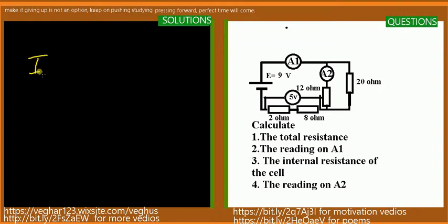So let's try this current divider rule to see if it is true, because Ohm's law says the current in parallel divides itself. If the total here is 0.5, it divides according to the ratios. The ratio means that if the resistor here is lower than the other one, this side will have higher current because the resistance is low, and this side will have lower current because the resistor is high.